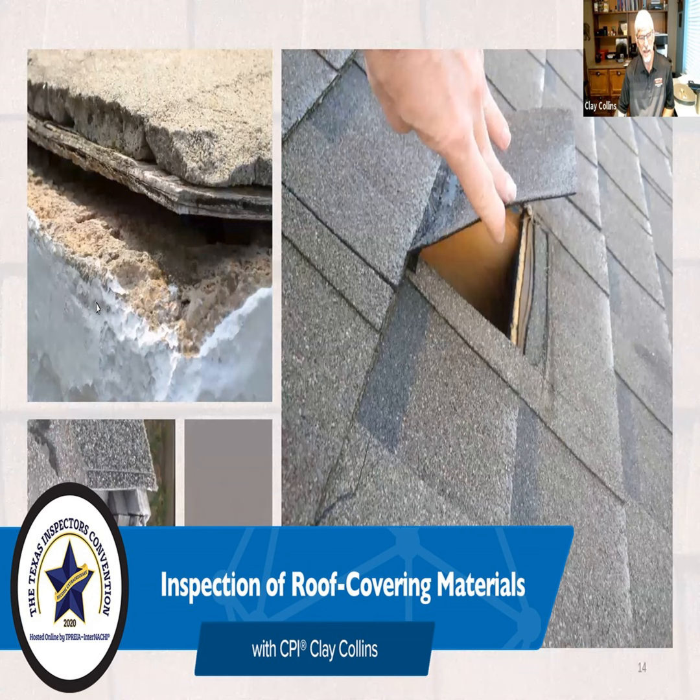But understand that H-clips are not required unless the rafters are spaced more than 24 inches on center. So the use of H-clips is more a convenience than anything else. I think that a lot of the older builders will be able to tell you that they just dropped a nail in there to create that spacing. So today we use the H-clips, but you'll also see in the illustration down on the lower right,